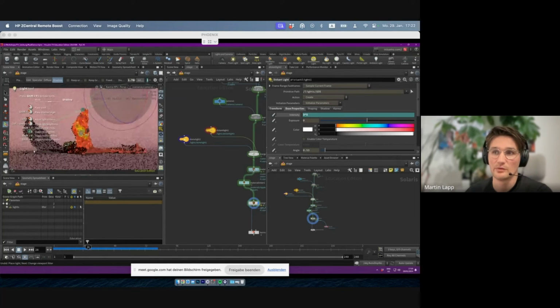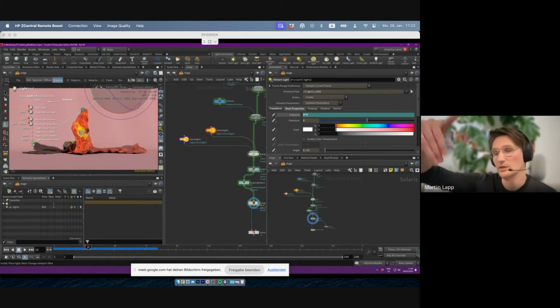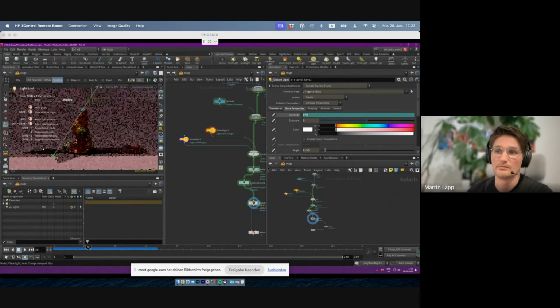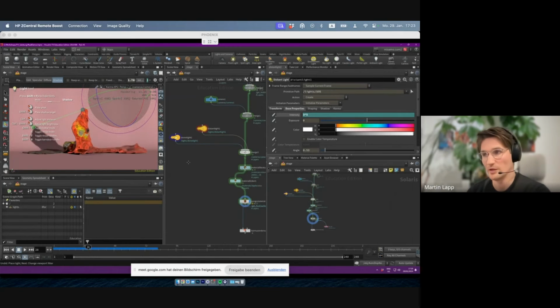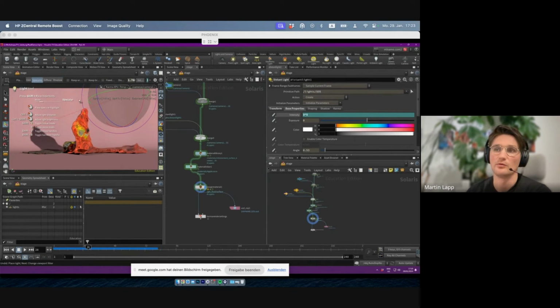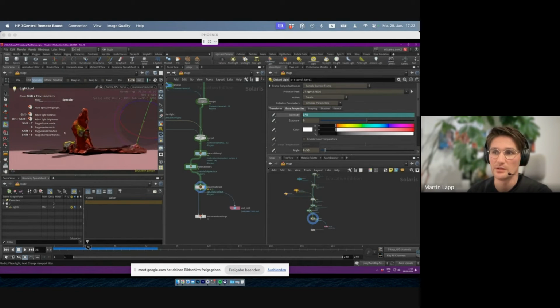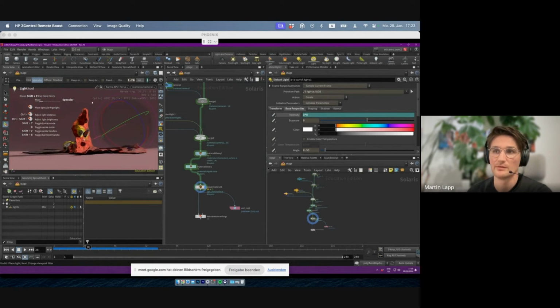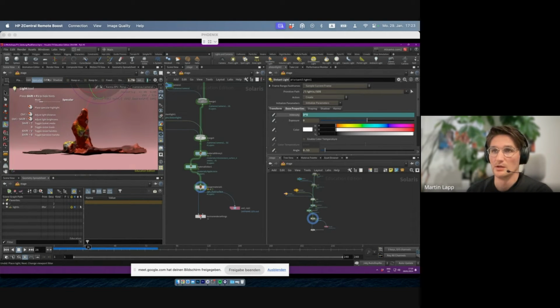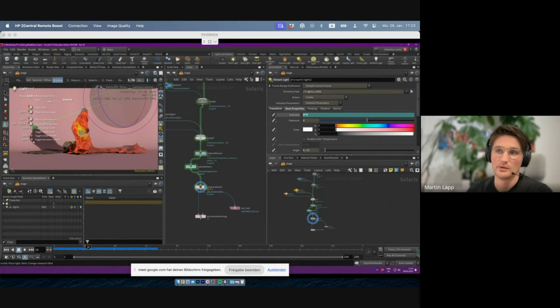And this is just one of the tools that make it quite easy to, if you have a plate and there is a tree and the tree throws a shadow on the ground, it's super simple to match the position of it. I think Katana has this now as well. Not sure if Gaffer has it, but it's super handy. And same goes for stuff like specular. So if I want to have a specular hit here, I can just click wherever I want to have a specular hit from each light contribution, and it just makes it super easy to have a base lighting going.